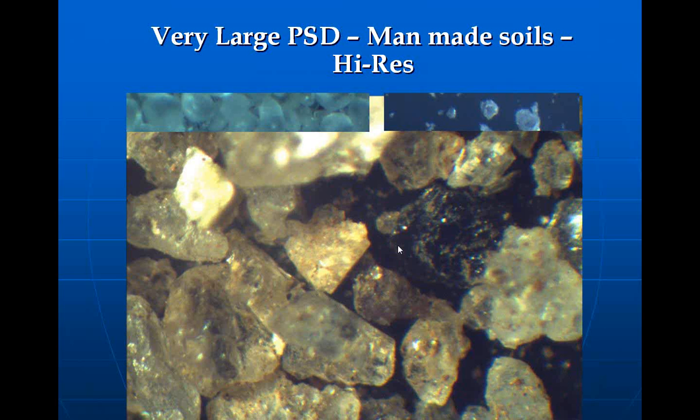But my point here is this is part of the explanation of why smaller commercial sites tend to have higher loadings and higher delivery because they have larger particles. And part of what we can start to infer is that we might not have to be quite so careful in our sizing on high-use commercial sites, small sites, as opposed to larger sites. Another thing we could infer, if the BMP is undersized, is that the small material is just simply washing out of this device. Now, I know where this particular sample came from, and the device is not undersized, but if it were, this would look very similar. There would be almost no difference. It's hard to tell without knowing the engineering data on the site. That's part of what the value has been of having the engineering data and tracking our devices.